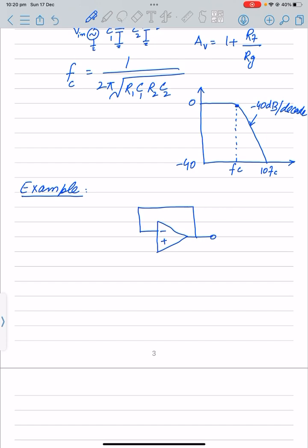However, we now have an R1 over here and R2 over here, and then a capacitor is also grounded, and over here we are getting an input signal. That one is the R1, R2 and C2, and then we also have one RC network over there, so that is a C1. So this is basically again a second order filter.